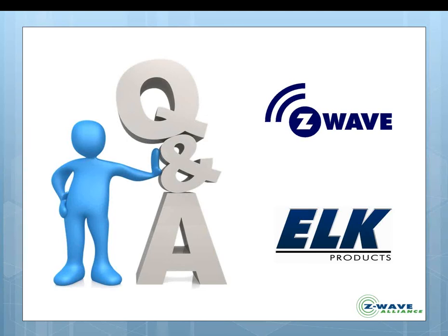If you're going to do it all off for an entire house where you may have 60 or 70 lights, now that may take a second or two, but again, customers will sometimes complain about that, and you can let them know that they've got a couple choices. They can have everything hardwired and spend literally tens of thousands of dollars, or they can go with RF and they can wait a second. So oftentimes a consumer will understand that very quickly when they figure out what the trade-off is between using a radio frequency communication, any of them, not just Z-Wave, and hardwiring, which is very invasive and very expensive.